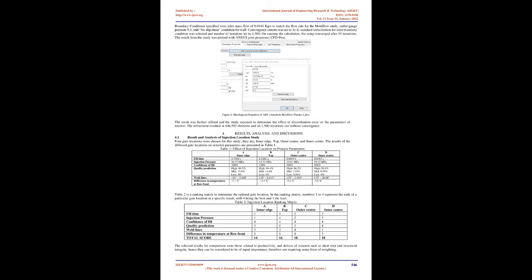Injection location is typically chosen to allow the melt to traverse from the gate to the edges of the cavity simultaneously to achieve an even fill. [19] In theory, the top gate, centralized at the middle of the molding, should result in an even fill and require minimal injection pressure as the flow length is about half the other locations. The downside of this position is an aesthetic defect, an obvious witness mark at the top of the molding upon